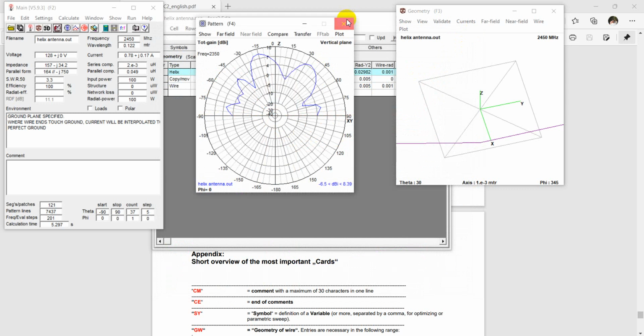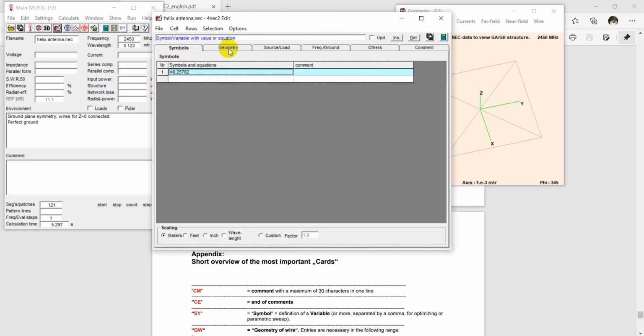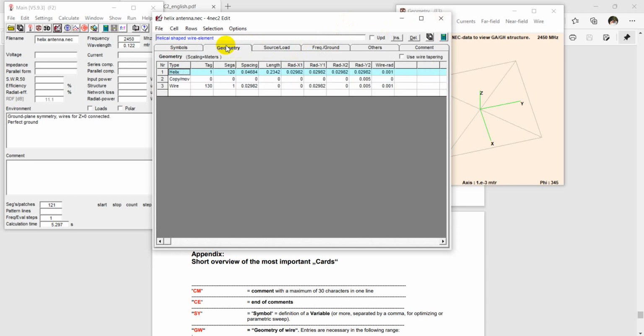That means you can only match the resonance frequency with the operating frequency in a dipole antenna, to design a dipole antenna or a dipole antenna over the ground, with this type of parameter. So you cannot match this resonance frequency to the optimum frequency at the same time. It's the information you have to understand, and you can see the radiation pattern.